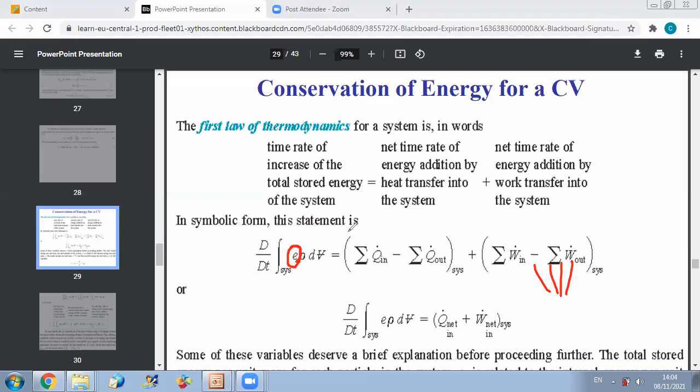We should know that if we apply the Reynolds transport theorem on this variable, then we'll end up with the following relation, that the variation of energy of the system is equal to the summation of all fluxes coming in of energy and work minus all fluxes getting out.